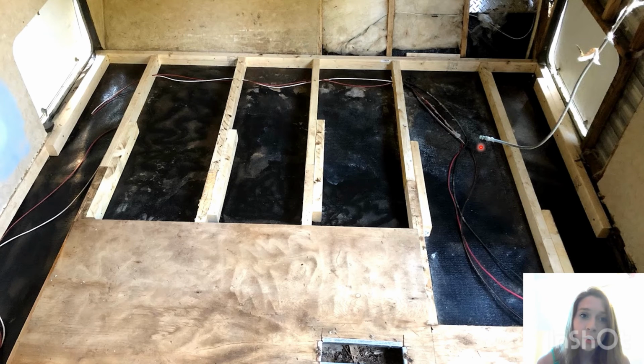Be sure to replace the anchor bolts if you're repairing any damage underneath the frame of the walls. I cut the old bolts off with an angle grinder and then added new bolts by drilling a hole from the outside frame up into the camper. So I had anchor bolts right here, and then there was one right there, and right there, and then one right there. So they basically hold the walls to the steel frame of the camper. So definitely make sure to replace those.